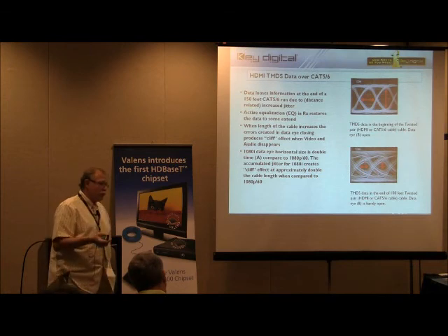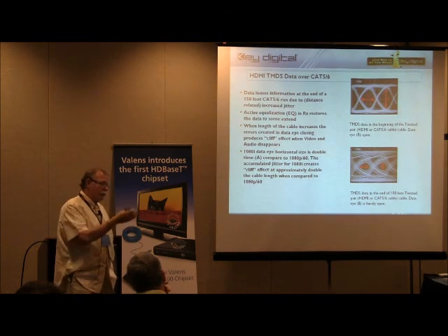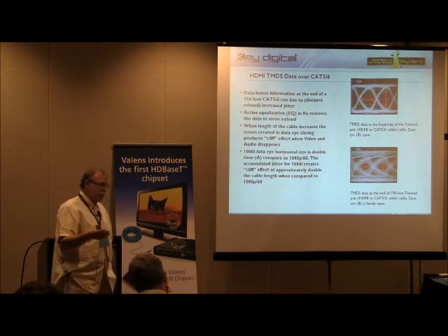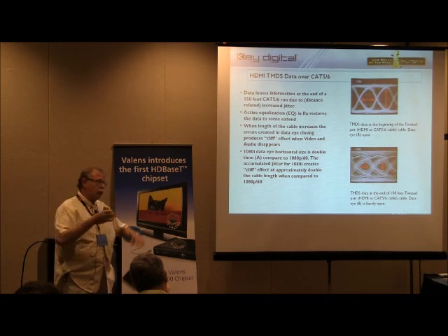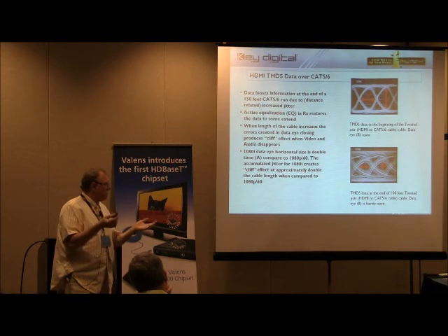But as you know, in digital transmission, the cliff effect is an interesting phenomenon, but you have to be careful with this, because if you use analog transmission technology and the cable becomes longer and longer, you gradually decrease picture quality. In the digital world, you still detect 1 and 0. The data on the cable is still very bad, but 1 and 0, the way they are represented on your screen, will look exactly the same.